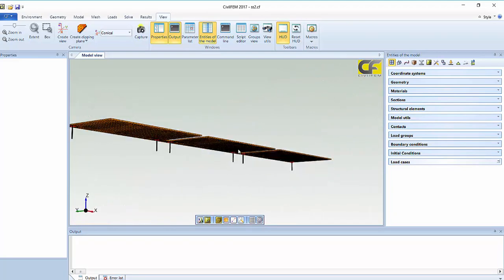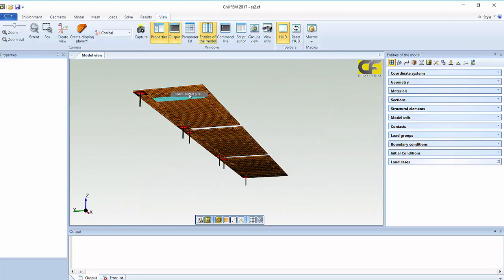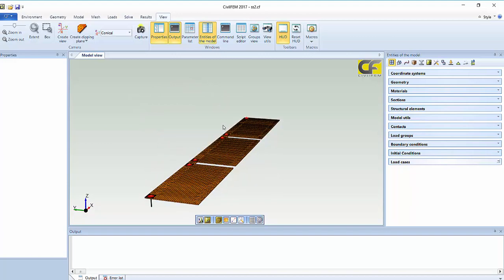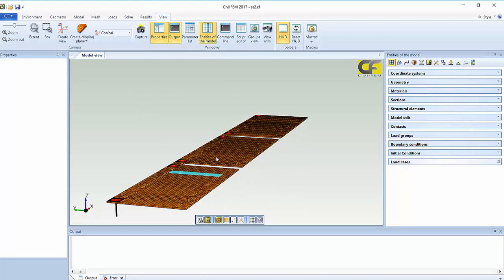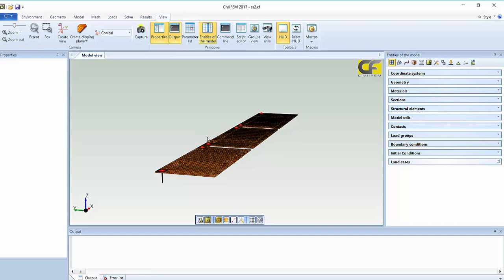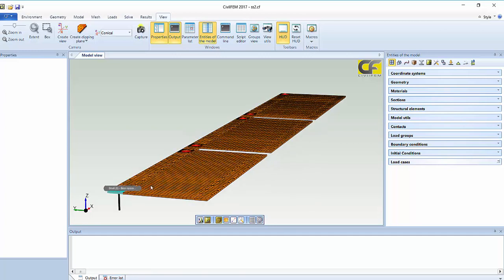Well, note that we don't have any sealing here in this part. We are assuming in this second stage we don't have any sealing resistance and the wind attacks in the vertical direction, and we want to know what happens now in the nails area.